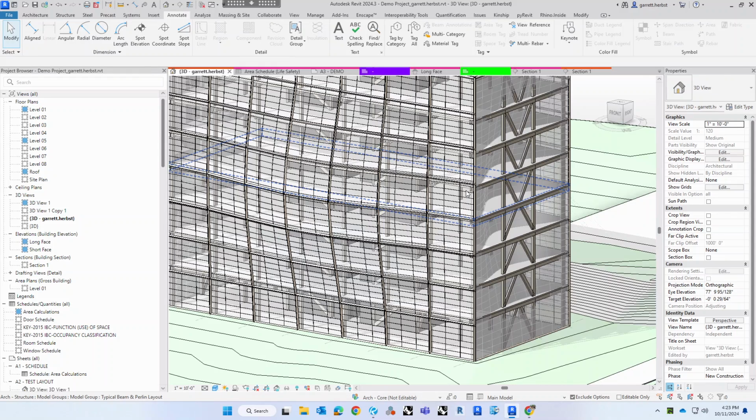The reason for that is that all the CLT is running this way. Along the long direction of the CLT panel, you don't want to have to go in and try to cut that. You really want to minimize your fabrication to the most minimal edge, so they can do that really easily with the fabrication equipment that they have. They'll just run the CNC and they'll have a visual model of the edge condition. Again, those are some of those tectonic things that you need to think about as well. It'd save a ton of money, save a lot of fabrication time, and work with your structural system.